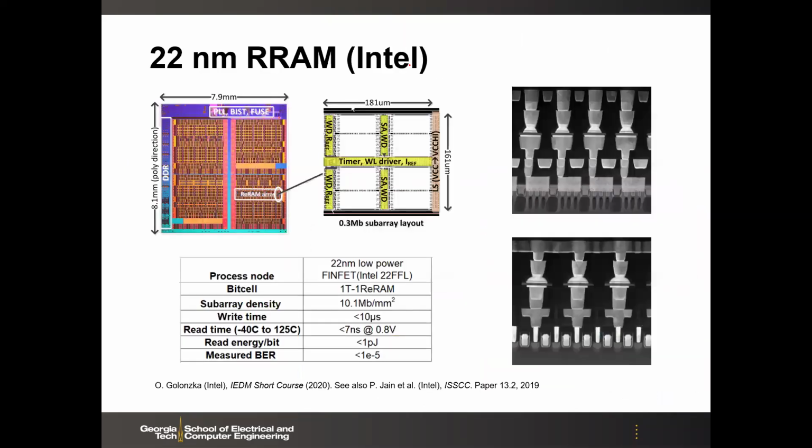At the same time, Intel also tried to invest in RRAM. So they published the ICC paper 2019, 22 nanometer RRAM with their FinFET technology. And then here there are some details. I'll skip those, the characteristics. You can read the table. So here you see this is the RRAM stack, and here is the FinFET. Okay, 1T, 1R. R is here.